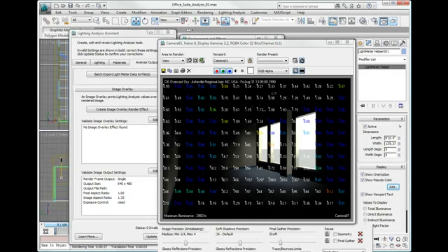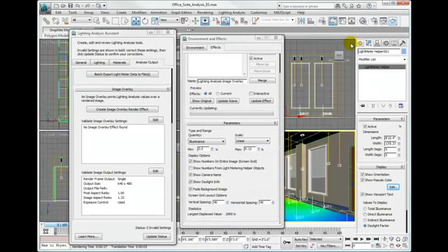So we'll go ahead and close the render dialog, and if we look in the render effects parameters rollout, we can see the largest displayed value was 2,714 lux. Let's go to our max value and type that value in. So 2714 and hit enter.